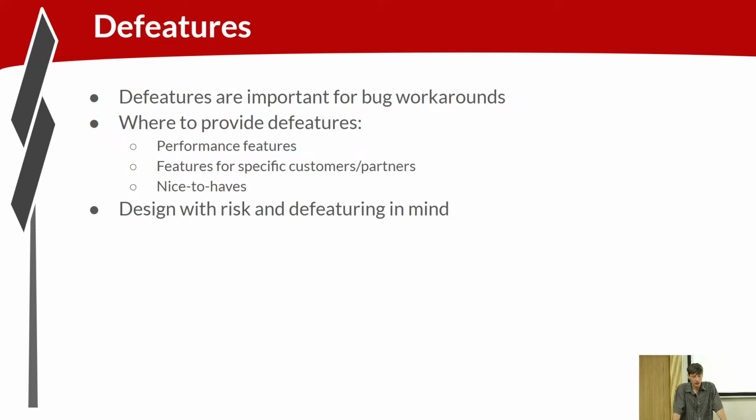So D-features are also important. When you have a bug in post-silicon, you don't want it to cost you millions of dollars. You'd like to still be able to use the silicon that you created. Mostly pre-silicon, you've verified the model to a certain level of stability. Mostly the bugs that you're going to run into post-silicon are in these gnarly corners. They might relate to some really bizarre configuration of the core.